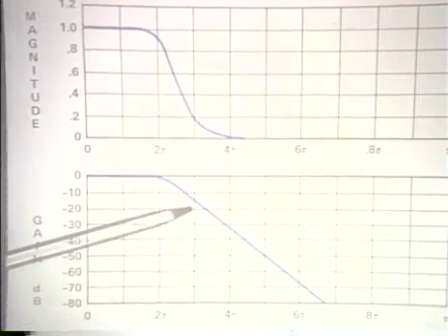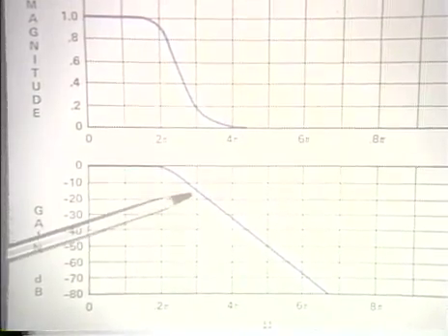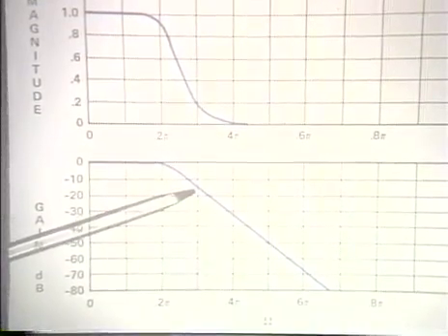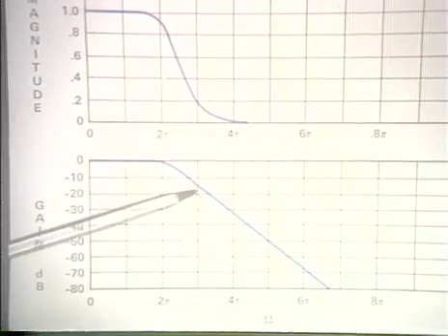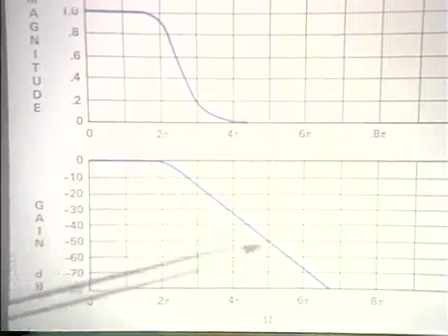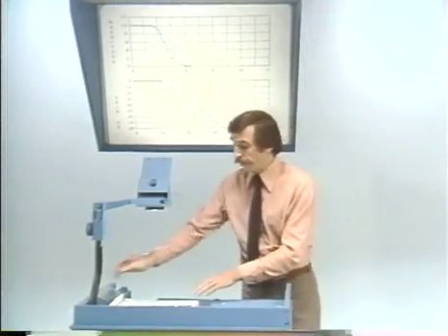And at 0.3 pi we should be down by at least 15 dB, and we chose the design so that we would exactly meet that edge. So we've met this point and exceeded this point, and this is our design. Now, let's just compare this with the impulse invariant design that we saw a few minutes ago.